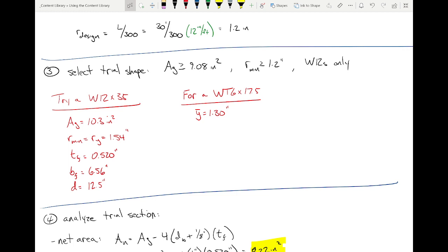And then, here's the thing. Now let's live in some reality. What if I picked the next member and the efficiency was 85%? What does that mean? The next smallest member didn't work. Say it again. Just use it. Exactly right. Again, the 90% is a good rule of thumb.